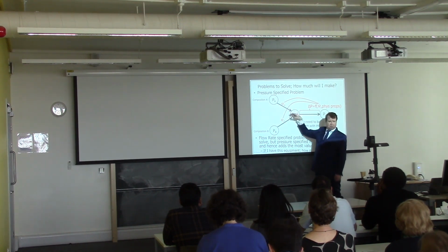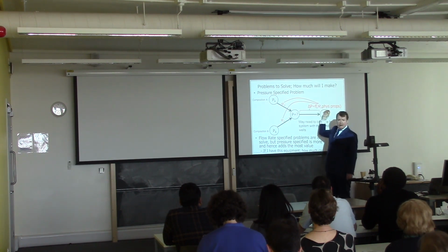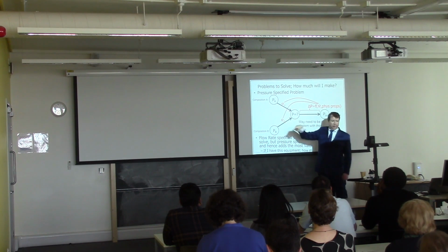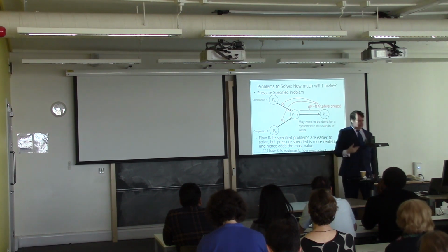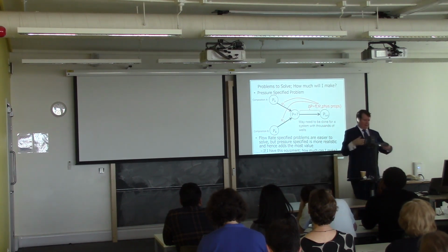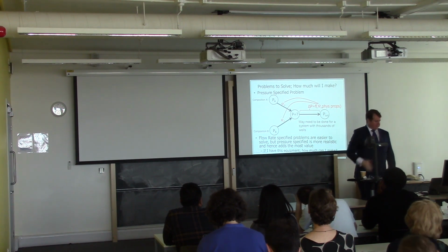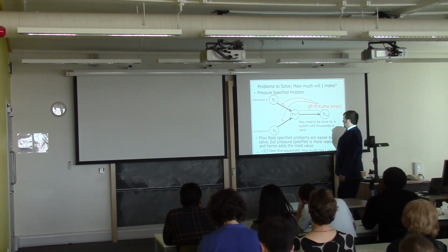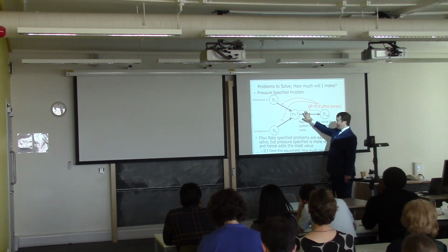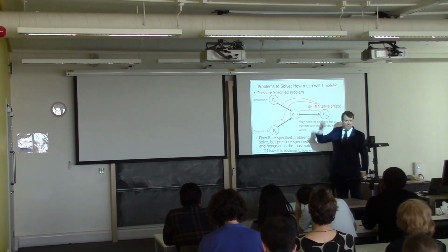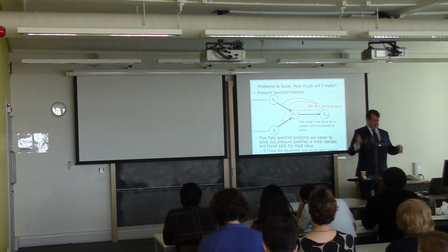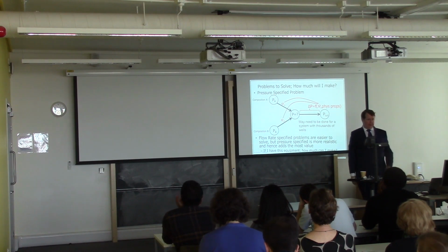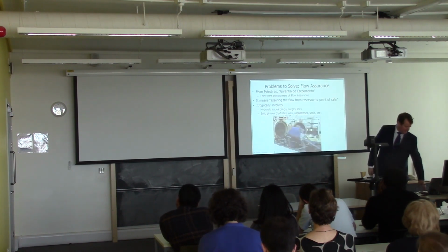I know these compositions. I know that I've got twice as this, and I've got that. It's all quite straightforward. And then I can back calculate what the pressure is. That would be simple. But calculating the compositions and pressures and flow rates at the same time is difficult, though it adds a lot of value to the design, because I want to know what if this is an 8-inch pipe or a 10-inch pipe, what if it's got a pump or not a pump, various other scenarios, and how much more will I make from that system.